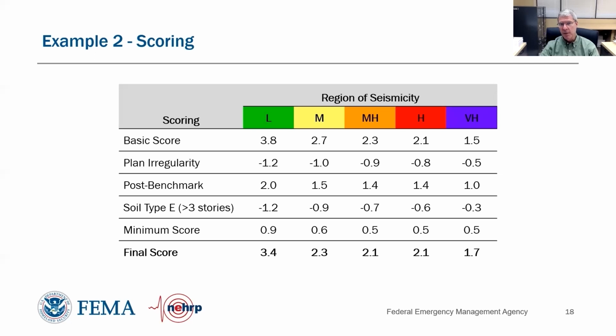If we had a new steel moment frame building that didn't pass our criteria, I would have very severe questions about how I use that, if a new building won't pass the criteria. And in fact, in all of these seismicity regions but one, the building does pass. Here's what I'd like to point out. Post-benchmark means this is a newer building built to newer codes. And part of that, as you know, for the design provisions is that if we have a poor soil type, our building foundation system is designed for those poor soils.